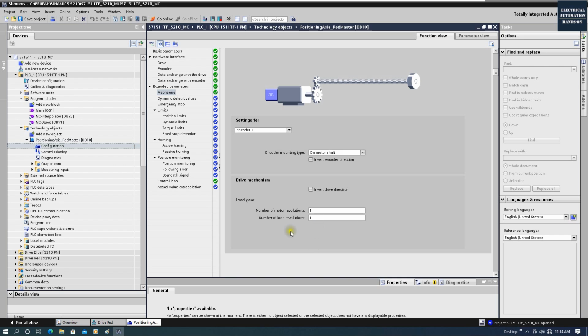Then you can directly measure the actual distance traveled or actual degrees spun from the load. Then you can roughly know, when you set 10 revolutions, 3600 degrees, from the motor spin, what the real distance or real angle moved from your load. Then you can immediately know the internal ratio calculation for this axis, from this mechanical setup.